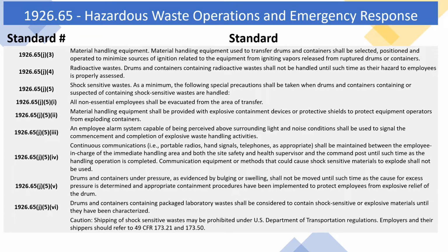1926.65 J5 5. Drums and containers under pressure, as evidenced by bulging or swelling, shall not be moved until such time as the cause for excess pressure is determined and appropriate containment procedures have been implemented to protect employees from explosive relief of the drum. 1926.65 J5 6.